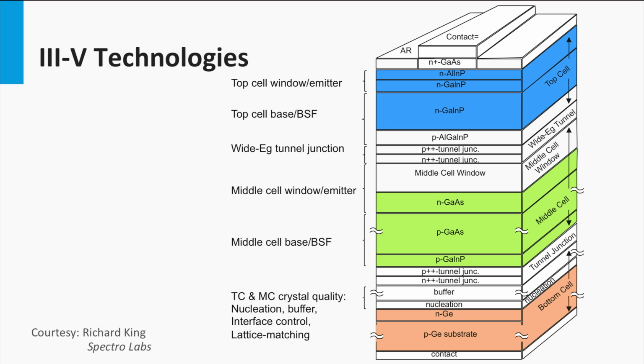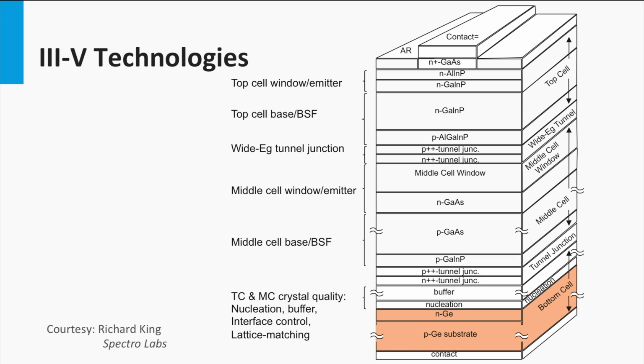How does a multi-junction solar cell work? The p-n junction at the window layer at which the solar light enters the PV device is called the top cell. As the spectral part with the most energetic photons like blue light has the smallest penetration depth in materials, the high bandgap junction always acts like the top cell. As the near-infrared light outside the visible spectrum has the largest penetration depth, the bottom cell is the cell with the lowest bandgap. This cell has to harvest the photons from the spectral part with the lower energetic photons.